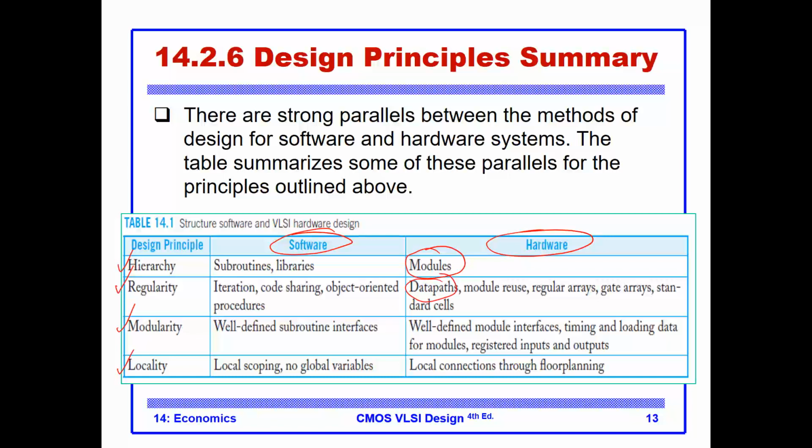Regularity: identify data paths, for example adders, multipliers, small ALUs, regular arrays, so that you can promote reuse. Modularity: you have to think of the interface, a very accurate, well-defined interface. And locality: anything local, you keep inside your design. It doesn't need to be exposed to the outside world.